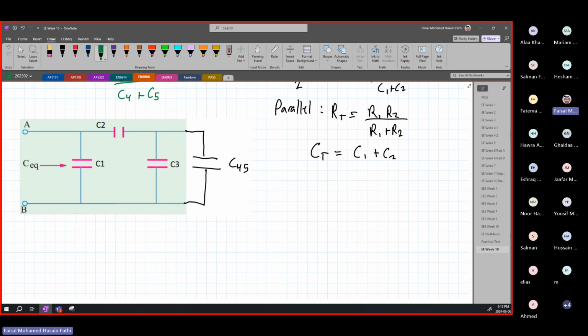It's very clear at this point because you have two connection points. You have a connection point over here and you have a connection point over here for both. So now they are connected in parallel because here is one connection and this is a second connection. So because they are in parallel, C345 is equal to C3 plus C45.